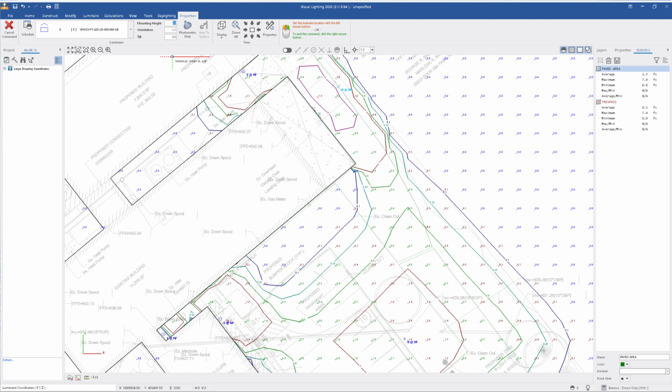Set the height. Nope, I put it in the middle of the building. No big deal. We'll just move it to our location right there. Still says we have a 0 somewhere. And this is part of the fun too. It's just the challenge of finding out where is this 0. So I'm looking around the edges of my paved area. It's typically what happens, and looking for any blue zeros like this.